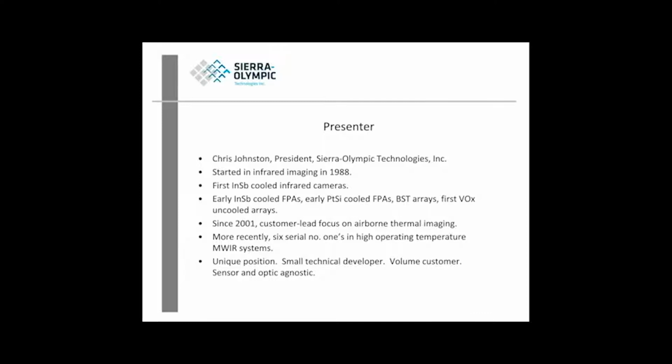These were 128 by 128 arrays in large liquid nitrogen dewars, and it was a miracle technology back in the late 80s. Experience with, of course, the InSb arrays, the platinum silicide arrays, BST arrays. All of those, platinum silicide and BST, are now kind of extinct, in fact. And then the very first uncooled microbolometer arrays, or VOx arrays.